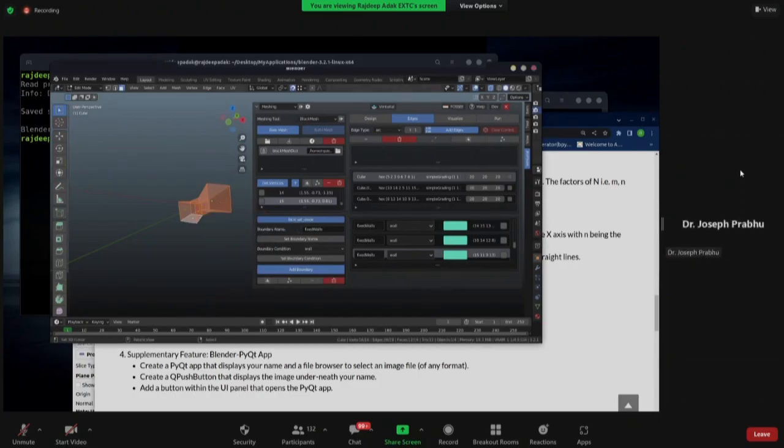Rajat, this Blender is a modeling software, right? Yeah, a 3D geometry modeling software. Here I can import an .stl file and I can create the domain and I can do the meshing here. You can open it up from STL, which is an option within Blender itself. But converting it into a blockMeshDict is where the parsing is required. That's why you have a separate option called Build Mesh.